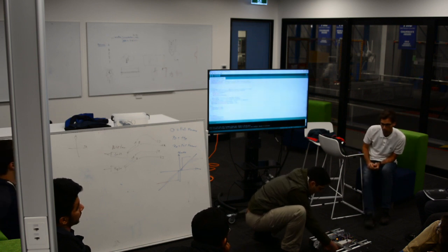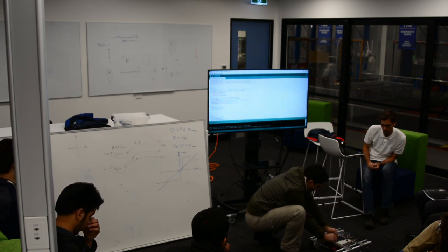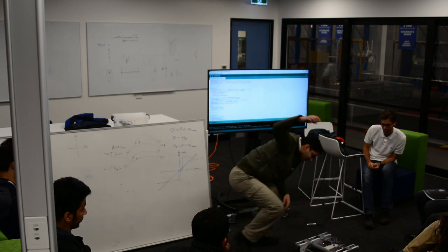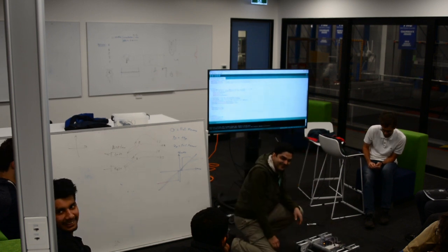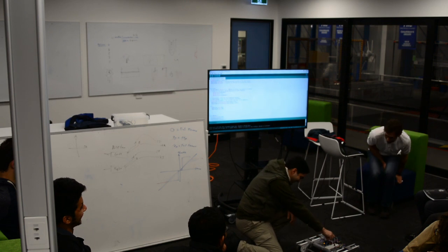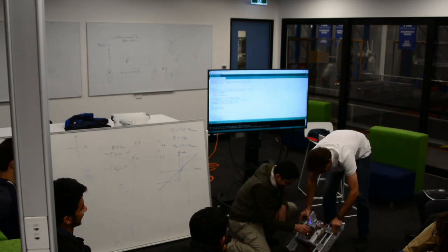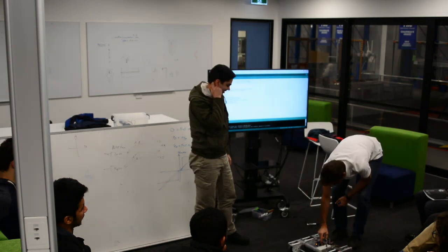Here, I'll lift it up. Yeah, I think maybe we'll just put it on the blocks. Get out of the way. Then we're not gonna see. Now we can do the reset. So this is at a gain of 0.2. It's a little straighter, it still does that turn at the end. And if we put it up on the blocks, we can look at the error signals.